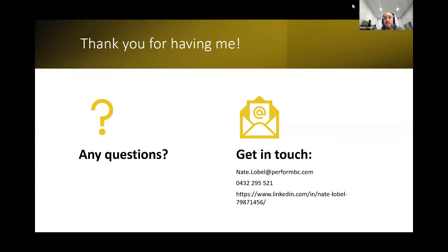They were that I mentioned reliance on other passengers to assist egress. Do I think that's sufficient in addressing it SFAIRP, or should other further measures always be introduced? The second direct message was, what are your thoughts on fuel loads, especially those that are traveling to and from airports? The third one looks like it was to everybody. It was, how is the changing characteristics of the population, aging, affecting fire engineering and infrastructure? And this next one is: post-incident, fire brigade are responsible for potential search and rescue in the tunnel. Should further consideration be given to increasing structural fire resistance of tunnels for this reason?